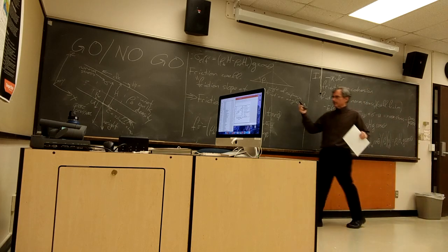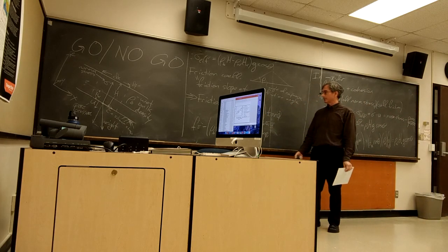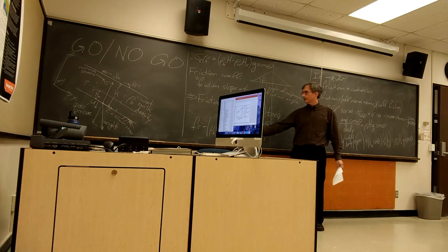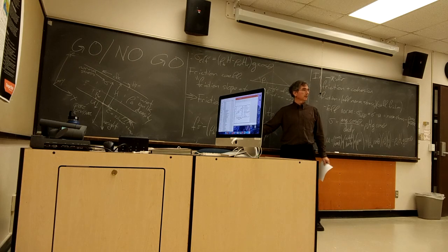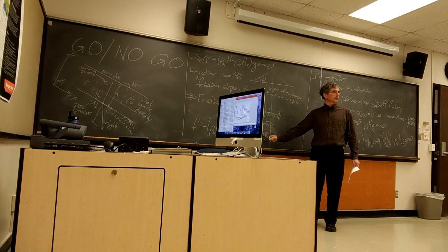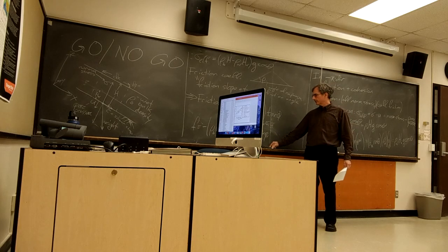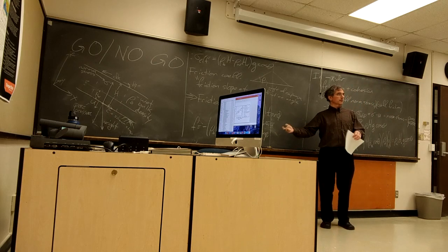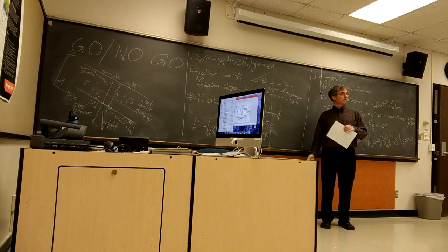So since it took us a few steps, let's remember what's here. We've got just the basic weight of the material, but we have to subtract off the pore pressure. We've got our friction slope here. That is our friction coefficient. And I've given it a minus sign because I said that it's acting in the minus x direction.